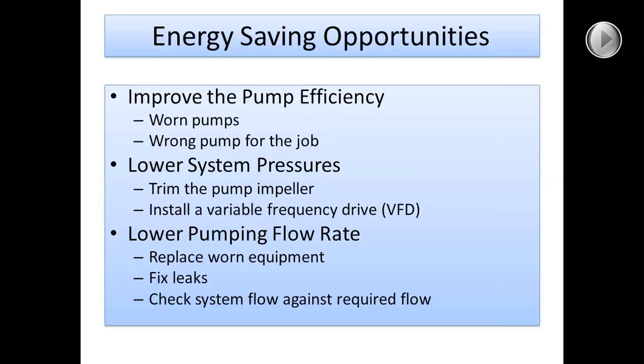And we came back and talked to these guys, showed them the low efficiencies that we calculated, and they were really surprised. They said, well, those well pumps, we just replaced the bowls and worked on them, and they're only 2 years old. Why is the efficiency so low? And the reason is because they were designed to operate at a higher flow rate than they were operating at, and just lift that water from down in the well to the surface with little pressure. But they were running clear to the left of their pump curve.